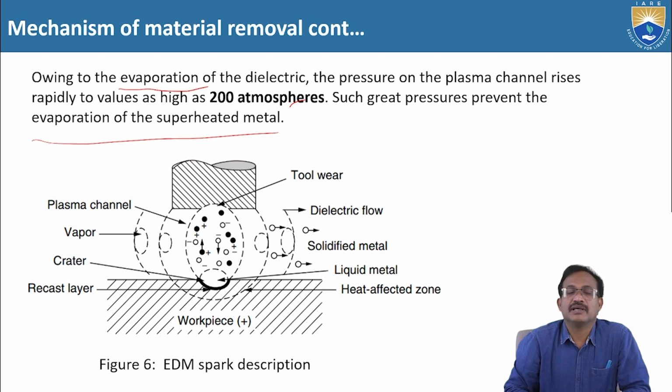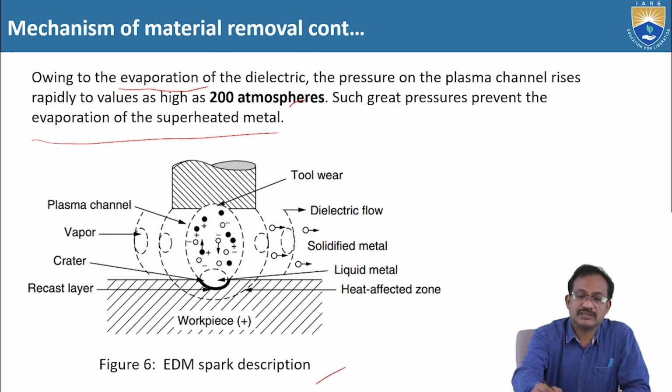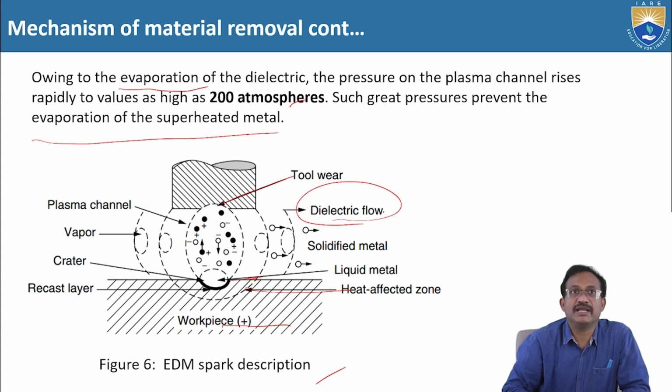Observe this electrical discharge machining spark description. See here, this is tool wear. This is the workpiece and this is the heat affected zone. Here you can see the crater, and here the liquid metal will form. Here the solidified metal can be seen, and between them the dielectric fluid medium will circulate.